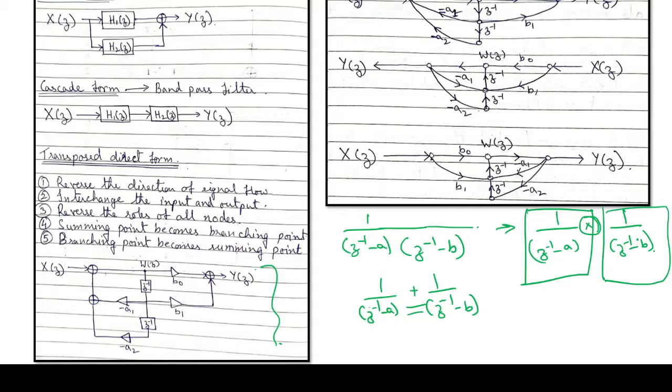Okay, but just for the sake of understanding, you look over here. Suppose we are having a realized filter over here, and we are having these z inverse terms which are commonly present for both input and the output. That means for performing the transposed direct form realization, we need to start with the direct form 2 realized filter, and from there we have to proceed.